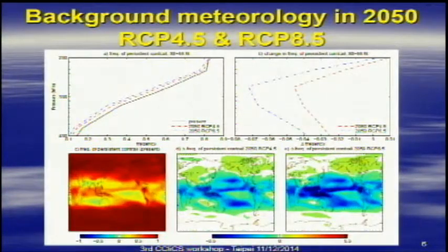There are two conditions. When the two conditions are met, then you probably have a good chance of seeing contrails over your head. First, of course, you need to have a flight over your head. Otherwise, you never see a contrail. Second, at a given altitude, the temperature has to drop below a critical temperature, meaning the temperature has to be low enough, and the air has to be moist enough. Otherwise, the water vapor emission from the aircraft will just evaporate. When the two conditions are met, we call that the persistent contrail condition.